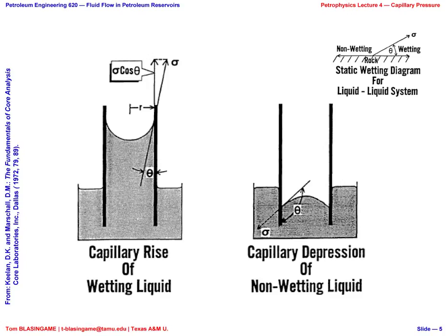Okay. You scored one goal. Now let's see if you can score another. Is this a function of temperature? Is it a function of pressure? Probably. Just a function. Okay, very good. You get a hug. That's a good way of putting it. It's a weak function of pressure. We usually don't consider capillary pressure to be a function of pressure. We consider it to be a function of temperature, saturation, and the properties of the medium. Okay? Very good. Everybody's done pretty well tonight.